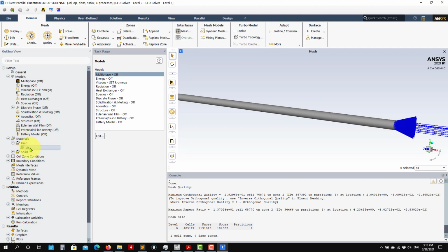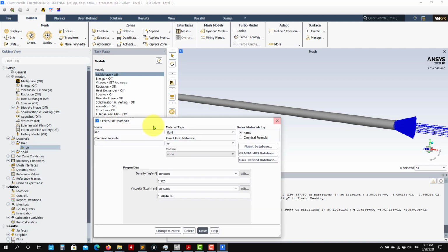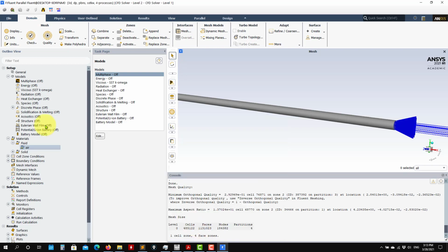Then go in materials, define materials properties. So again, we say this one like this, and this one should be 10^6 to give a Reynolds of 100,000 using an inlet velocity of 1. So here, then here, nothing to do there.